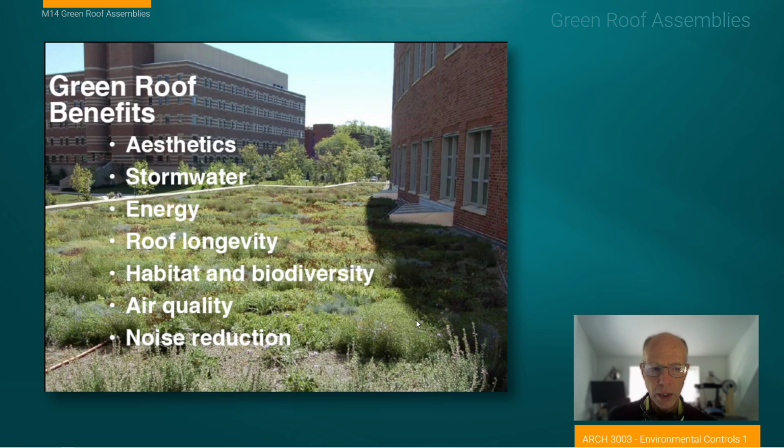They have a great aesthetic, obviously. They help us manage stormwater. They create cooler surfaces as opposed to reflective or roof surfaces that aren't reflective. And so that manages heat island issues. They preserve the longevity of our roofs by protecting the rubber membrane from UV exposure.